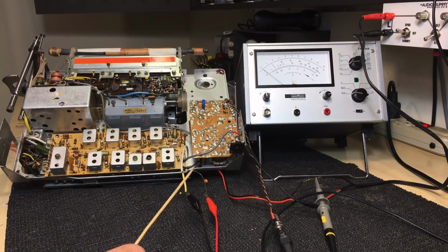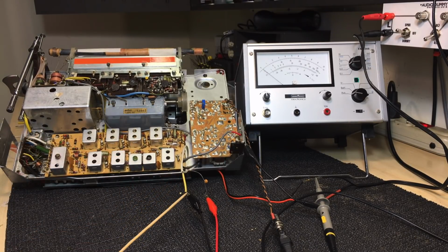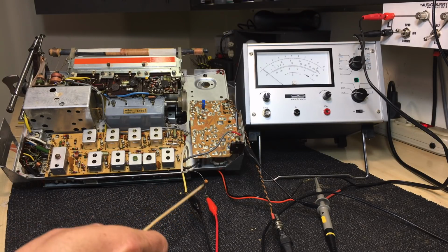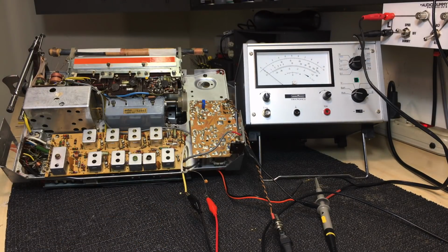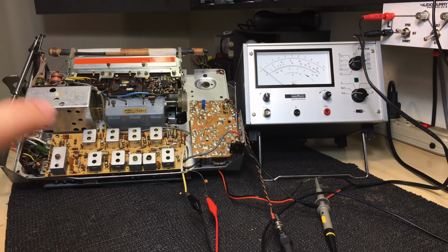The only thing I desoldered was this RF front end, and I'm feeding the signal generator, the ground to its ground, and the signal to the one end of a 4 picofarad capacitor. I'm going to switch on the signal generator. I've got everything ready, and I want to show you just to make sure that we can get a signal and that it's visible on the scope. In other words, if it's audible and visible on the scope, we know we can measure it with the AC voltmeter.